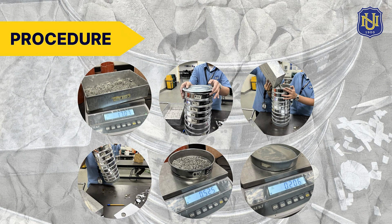The total graded sand is then computed and the percentage error between the initial and final weights is determined. The same procedure is repeated for gravel, using the sieving instrument intended for coarse aggregates. During the experiment, careful handling of the sieves and accurate measurements are necessary to avoid loss of materials and incorrect results. Proper recording of data is also important because the gathered information will be used to analyze the grading characteristics